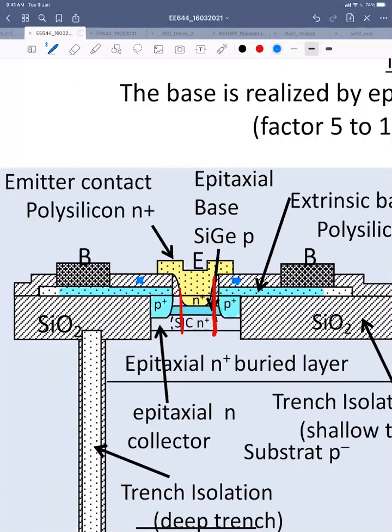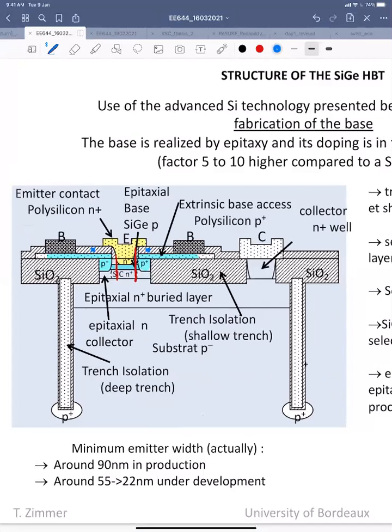And the collector, when we're talking about electrons being injected, electrons are going through all these things and collected here, right? So this part is also contributing to a resistance. So that's the reason I made my collector this way. This is called the buried collector part. This part is buried here, and this buried collector is made of highly doped N plus, so that RC, the extrinsic collector resistance, is low, right?